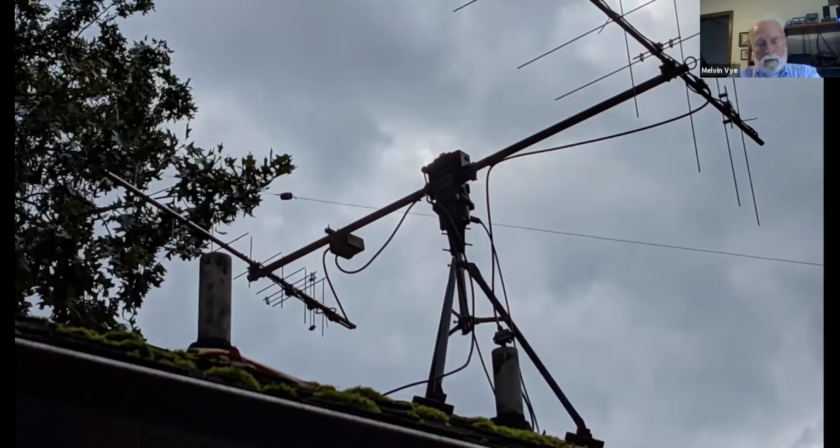And if we didn't use circular polarization, we would see some deep fades in spin modulation as the satellites float around. And also there's a thing called Faraday rotation, which is the tendency of the polarization of a wave to change as it propagates through space. So when possible, we use circular polarization on our antennas, and that tends to limit the fade as the satellite tumbles around. And it's mounted on a 5500 ASL rotor, which is what you see here.